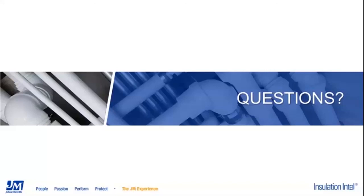All right, excellent. The next question we have, Natalia, I'm going to send this to you: what is the best practice for installing aluminum jacketing to avoid water intrusion? We prefer to see it installed without screws or rivets penetrating the jacket. Is lapping the layers and banding sufficient, or should tape or mastic or silicone be used?